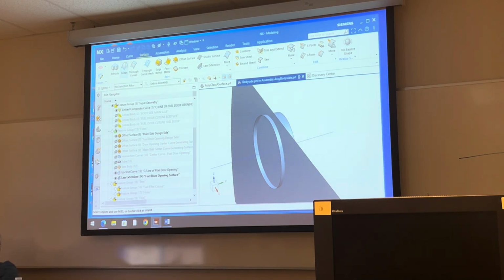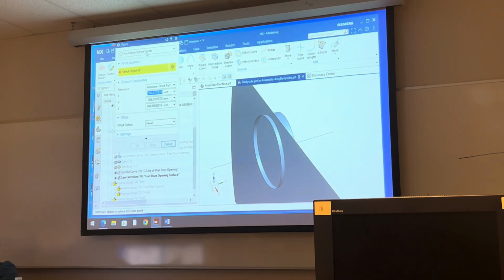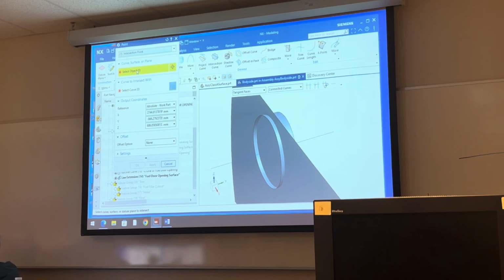So I'm gonna start out by making an intersection point. I'll go to the curve tab, here's point. I can do an intersection, project intersection point. Okay, now remember when you're doing an intersection point with curves, the second thing you pick has to be a curve, right? I know I'm gonna pick this line and that surface, but I don't wanna pick the line first, because the second thing has to be a curve. You learn that the hard way, right? So the first thing I'll pick is that slab, second thing I'll pick is that curve,